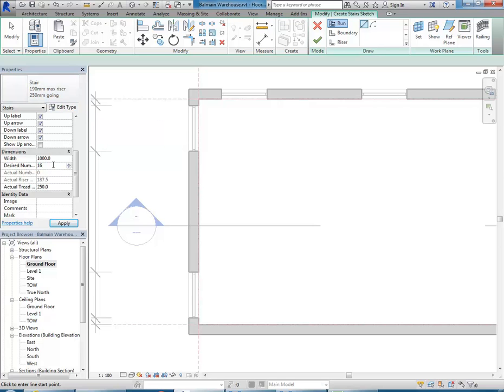And so it's worked out that with the 3 metre floor to floor height that we've got, 187.5 is the maximum height for rises. So when you're doing your stair design, that's something to bear in mind. But in this case, we need 18 rises. So that's what is existing.